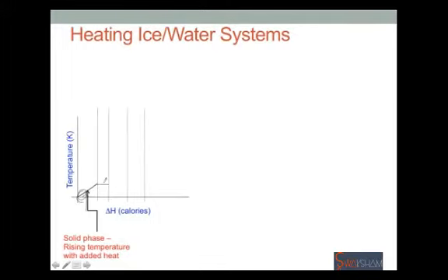After a certain point, once it gets to a certain temperature, we see that it still continues to take in energy, but the temperature doesn't rise anymore. In addition, we see that this material is gradually transforming from a solid-like state to a liquid state. So the ice is melting. So in this region, we see that the temperature isn't changing, it's taking in heat, and the ice is melting. Once all the ice is melted, we see that the temperature begins to rise again. So this is all water state, at the same temperature at which it melted.